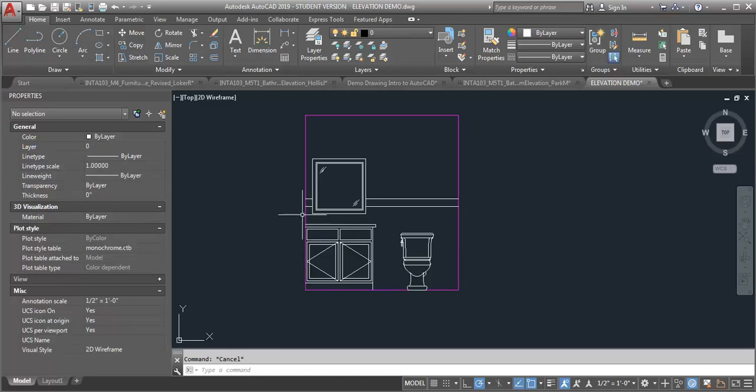This perimeter line represents the ceiling, the floor, the walls, and these are things that we would be cutting through basically when we're creating an elevation view. So we want that to be the heaviest line. If we were cutting through the side of a cabinet, and we'll have that happen in the kitchen elevations, that would also be in that heavy line weight. But in this case, it's just going to be the outside perimeter.